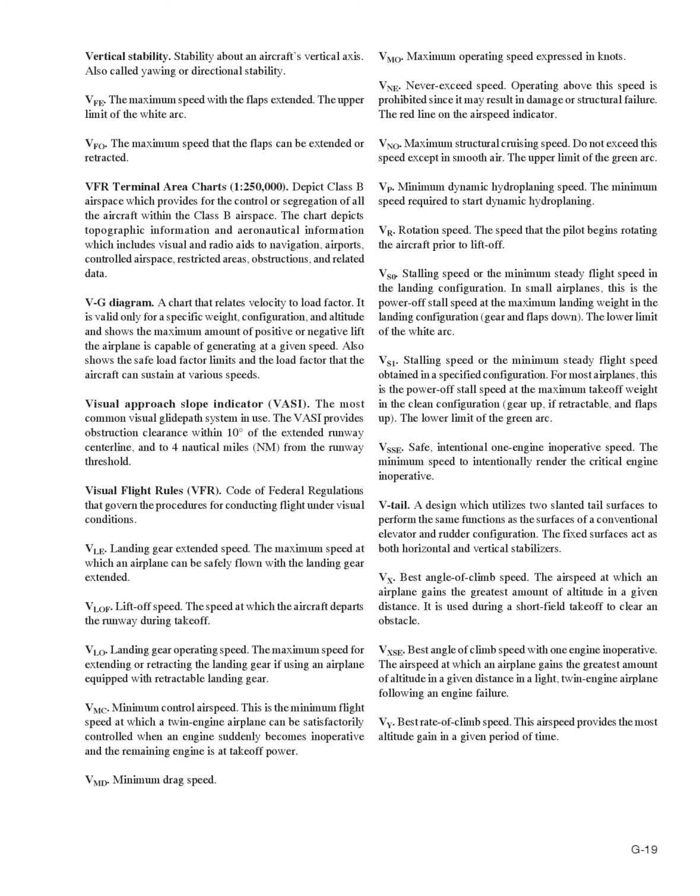VY. Best rate of climb speed. This airspeed provides the most altitude gain in a given period of time. VMC. Minimum control airspeed. This is the minimum flight speed at which a twin-engine airplane can be satisfactorily controlled when an engine suddenly becomes inoperative and the remaining engine is at takeoff power. VMD. Minimum drag speed.